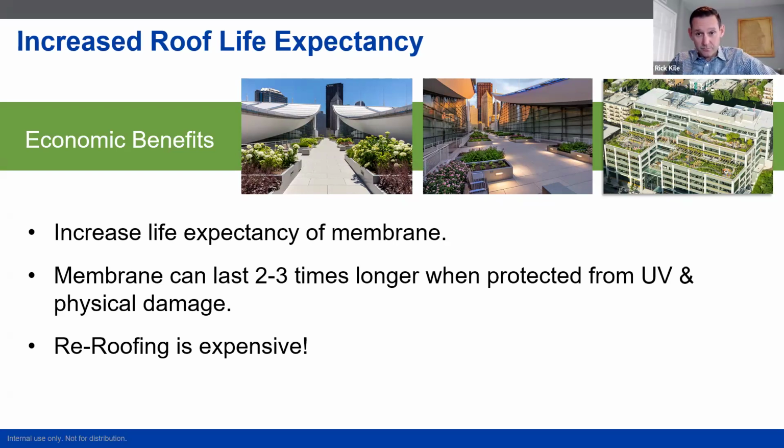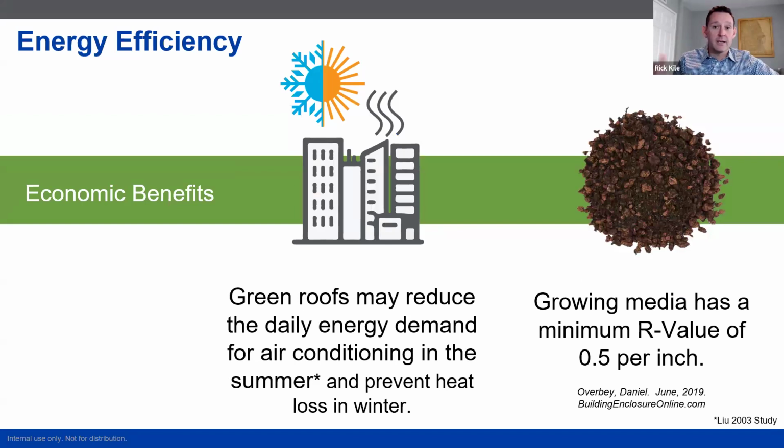Re-roofing is extremely expensive when you consider that maybe the tower cranes, the construction logistical equipment that was on site during the initial construction is long gone, and trying to get those materials to the roof, get the labor force on the roof, get the old roof materials off, the new materials back onto the roof, not to mention potential downtime for the structure. So the longer an owner can put that off, the better. And so a vegetated roof can be a great way to help extend the life expectancy of that membrane.